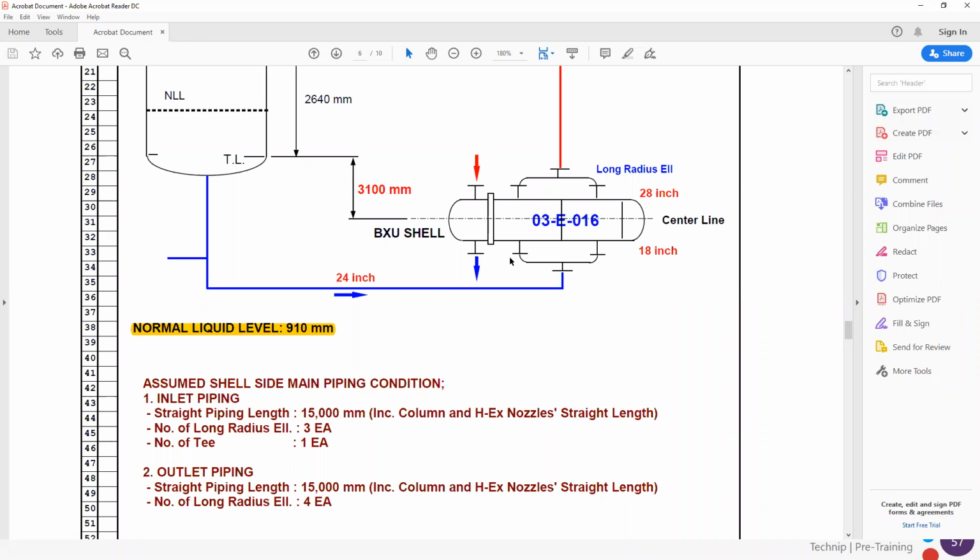Yeah, so there are priorities when you select. It's not only fouling, and that's the override criteria. No, the pressure drop is more important. Exactly. In this case, we have a process constraint, which is the pressure drop. So it means we are adapting the thermosiphon to the process requirement.